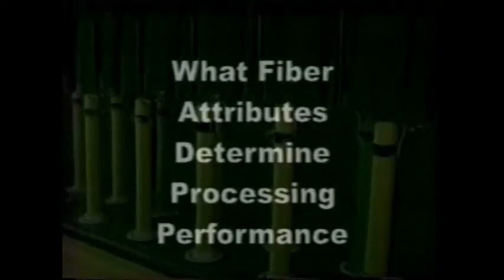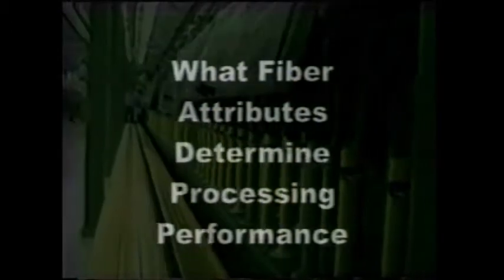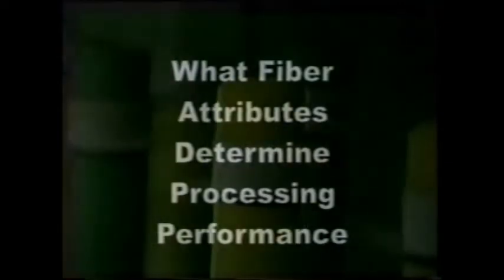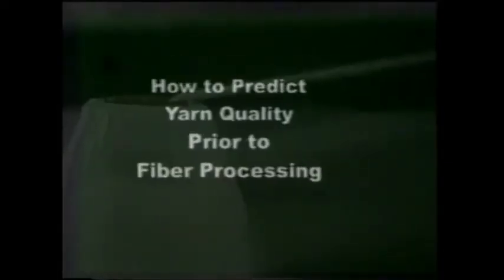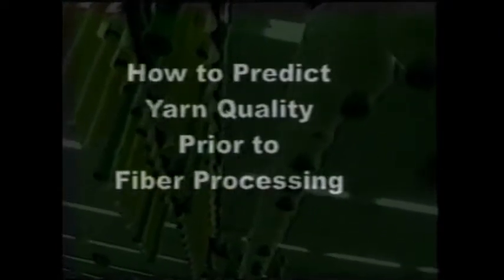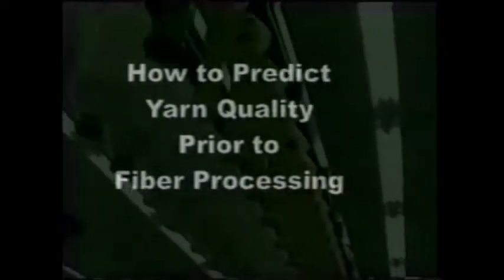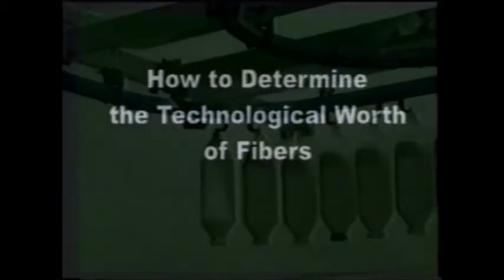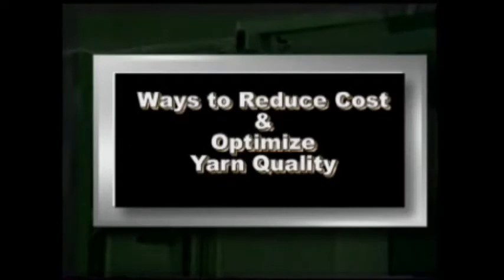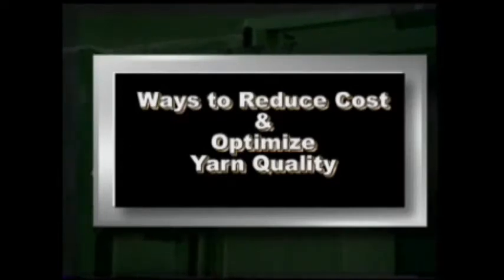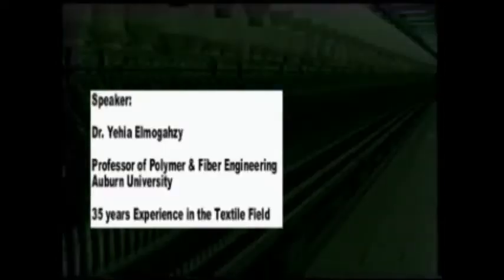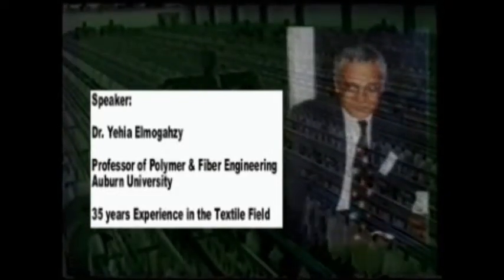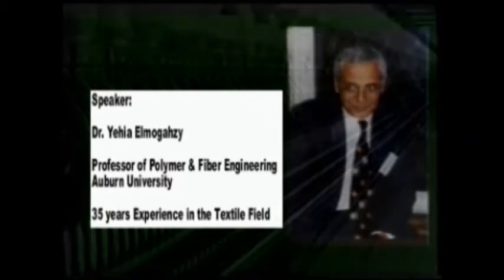The fourth part deals with fiber processing, starting with harvesting and ginning and going into cotton mixing and blending. All stages of spinning preparation, including opening and cleaning, carding, drawing, combing, and roving, are covered in great detail. Different types of spinning such as ring spinning, compact spinning, rotor open-end spinning and friction spinning. The course will also cover effects of yarn and fiber characteristics on textile fabrics.